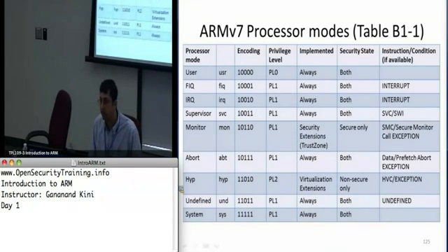It's still not on mobile phones today, but it has hardware extensions for virtualization, and it has large physical address extensions, LPAE. So those chipsets will have the hypervisor mode enabled. And so it depends on the vendor's implementation again. But there's a call called the HVC, which is the hypervisor call, to enable the hypervisor mode on the processor.